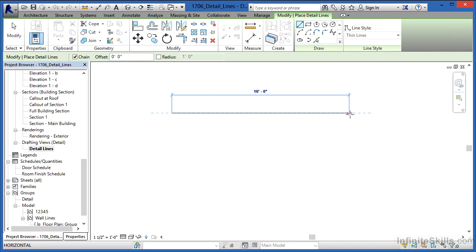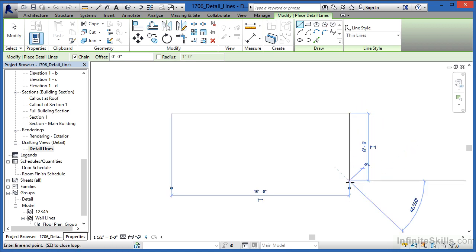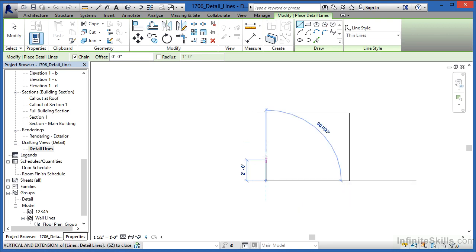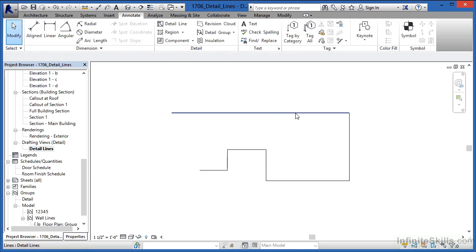The exact length for any of these lines I'm getting ready to draw doesn't really matter, so I'm just going to click here. You'll see that we now have a line on the screen. In fact, if I start to draw down like this and then click again, we'll start to draw one line immediately after another line. And to get out of this, I can just hit Escape on the keyboard twice.